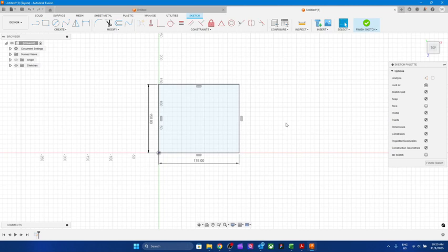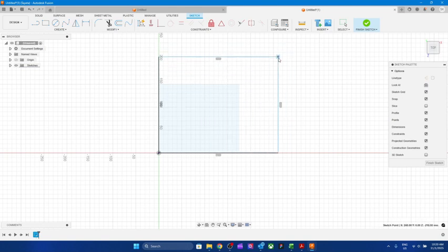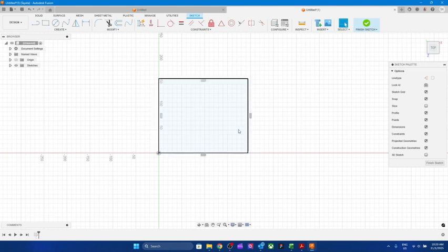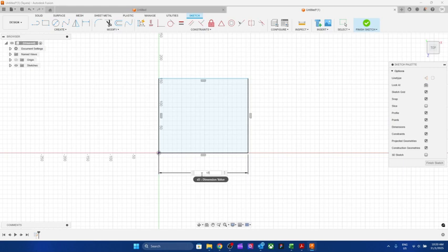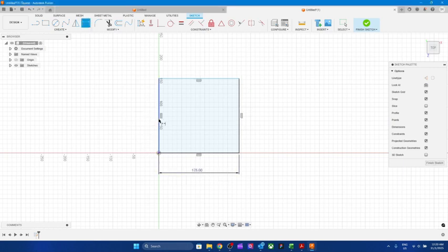Wait, doctor, how did you add the dimensions? Okay, how did I add the dimension? Simply, I will delete the dimension for you now. Okay, look, if there is no dimension, I can stretch it anywhere. So I want to add the dimension. When I created it, it automatically came, but imagine you don't have a dimension. I'll simply go on to sketch dimension. I will select this line and I will put 175 this way, and I will add, select this line.